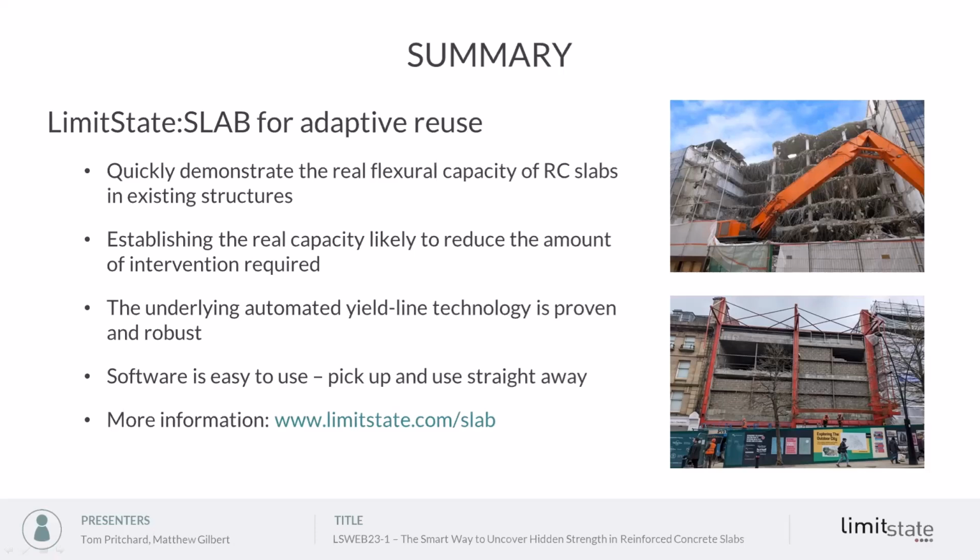So the first question is, is geometry optimization considered in the software to get a more accurate solution? So Matthew, I think, wants to answer that one for us. Yeah, so good question. The answer is no. Geometry optimization is really good at sort of rationalizing a yield line pattern, making it look prettier. It doesn't make a very big difference in terms of the answer, certainly with the nodal resolutions that we're talking about. So it's not going to make a very big difference. It's going to reduce it by 0.1% or something of that sort.